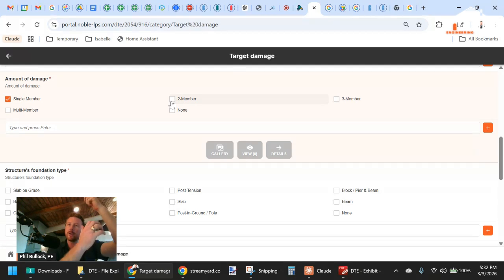This could look like you going over to the damage and putting some weight on the member itself where the crack is, putting some weight on the ceiling joist if you see there's a notch or a cut where there's a problem, or going on the roof and pinpointing the area of concern and seeing if there's a soft spot or a spot where bowing and deflection is occurring because of the problem.